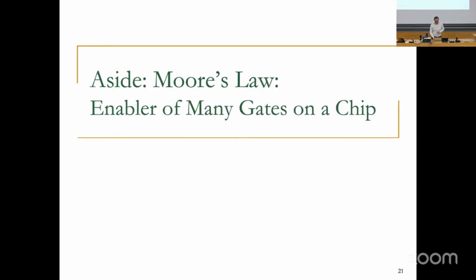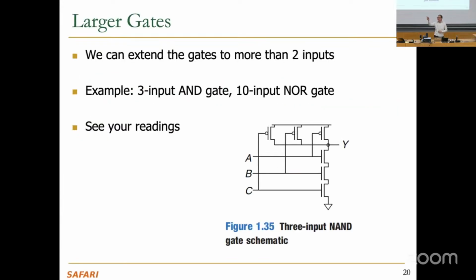Okay. Any questions? Yes. I mean, they could. Especially when you're powering things up, for example, you may have some current spikes, and they may have impact on the circuit. Certainly, they have impact on the lifetime of transistors. No question about that. High voltage, high current, those actually affect reliability of the circuits, especially when the circuits are very small. But these are very good questions that we're not going to get into. We may get into something similar at some point, but not yet.